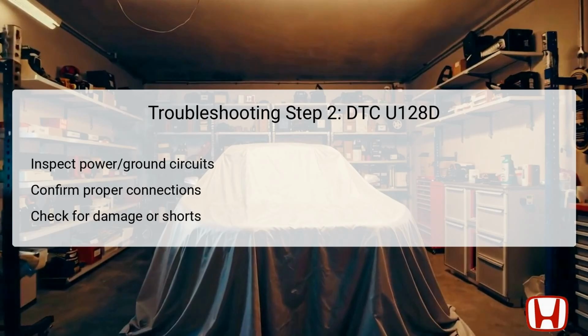It's essential to confirm that all connections are secure and that wiring has not become loose or corroded throughout their length. Checking for physical damage such as fraying or shorting in the wires is equally important, as these defects can also disrupt electrical pathways. This inspection process is essential because it helps find the root cause of the communication issue, leading you toward a successful resolution of the DTC.